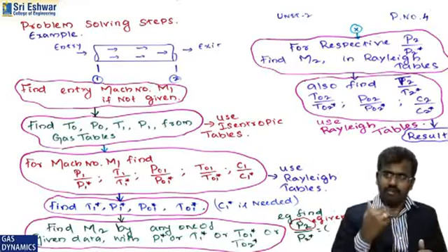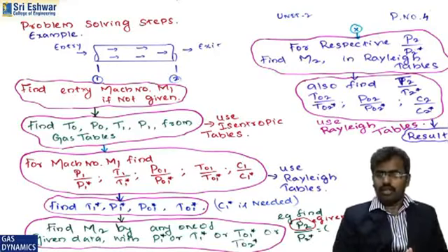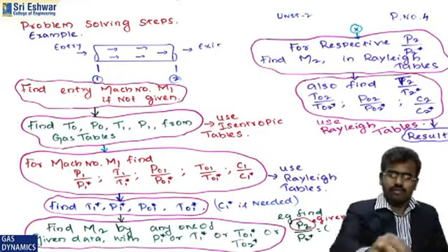Now you can find the value of P2 by P2 star using your Rayleigh table. Then you can check your answer with flow is isentropic. You can get the result of T02, P02, C2, even T2. You can find the section 2's parameters completely. This is the procedure to solve the problems.